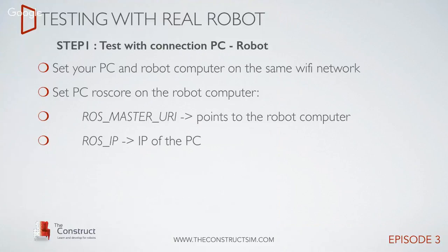Yes, so Arduino, of course, if you connect the sensors to the Arduino and you make the electronics, or you buy the proper boards that directly connect to the Arduino and make those sensors, that's okay. Then you will have to put ROS on Arduino in order to control those sensors from ROS. Remember, it is possible. It did exist, ROS Arduino. So you check on the web and then you will find it.